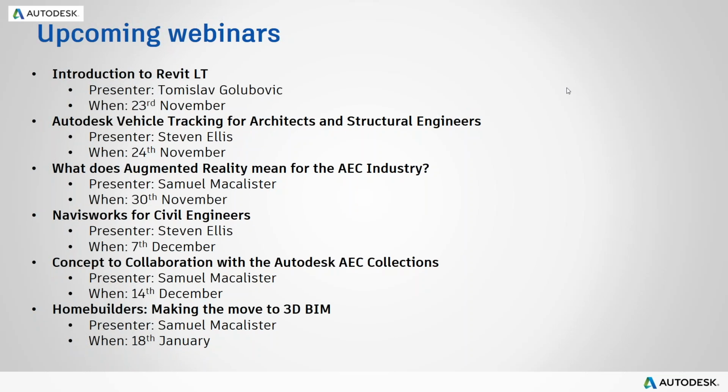Do we have any other questions? Gary James has asked, are the connections tied back to Dynamo? Can they be altered within Dynamo? No, the connections are not tied back to Dynamo itself. You can't do the connections with Dynamo. Like I said, you do your beams, your columns, and any other purlins that you wanted to, and then those connections link those members together. If those members change via a Dynamo script, then the connections will change because they're linked back to those items.